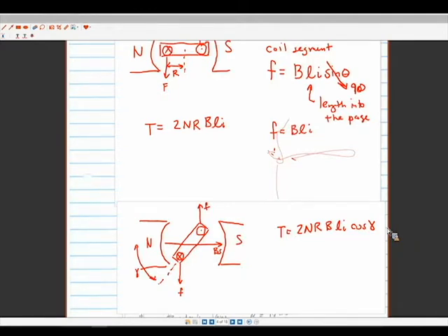All right. So this entire term out front has a name that's often used, and you'll see this on a lot of spec sheets. And this is oftentimes given by K tau, or what's called the torque constant. All right, and it's in units of Newton meters per amp.